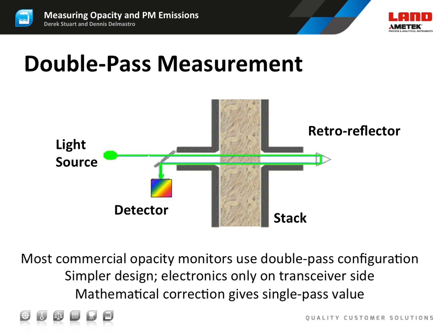Most opacity monitors are designed to be double-pass monitors. This simply means the light beam makes one pass through the flue gas, hits a mirror called a retroreflector, and passes back through the flue gas to the signal detector, thus a double-pass system.